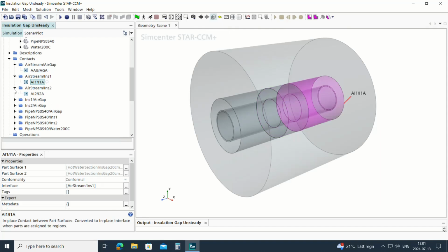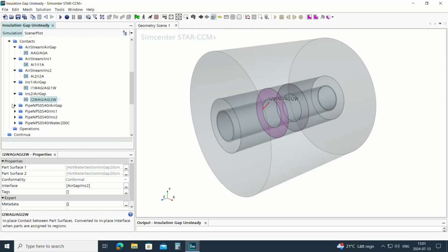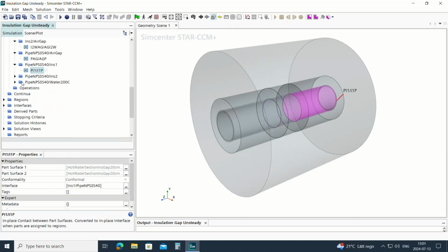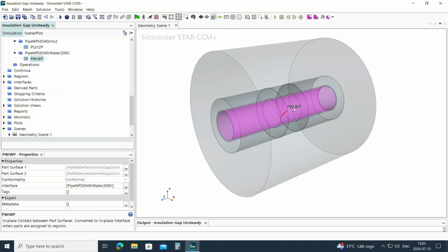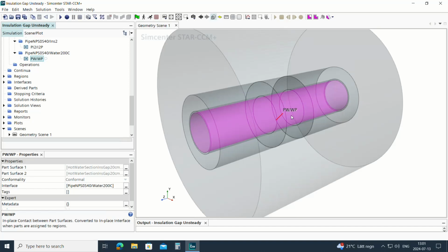So if we don't have the contacts, then we can't use the interface generation using contacts option. Okay, so by splitting the patches and creating the proper boundaries, we can make sure that all the contacts that we require are captured. Okay, and again, if you monitor the naming, you can see if they make sense.